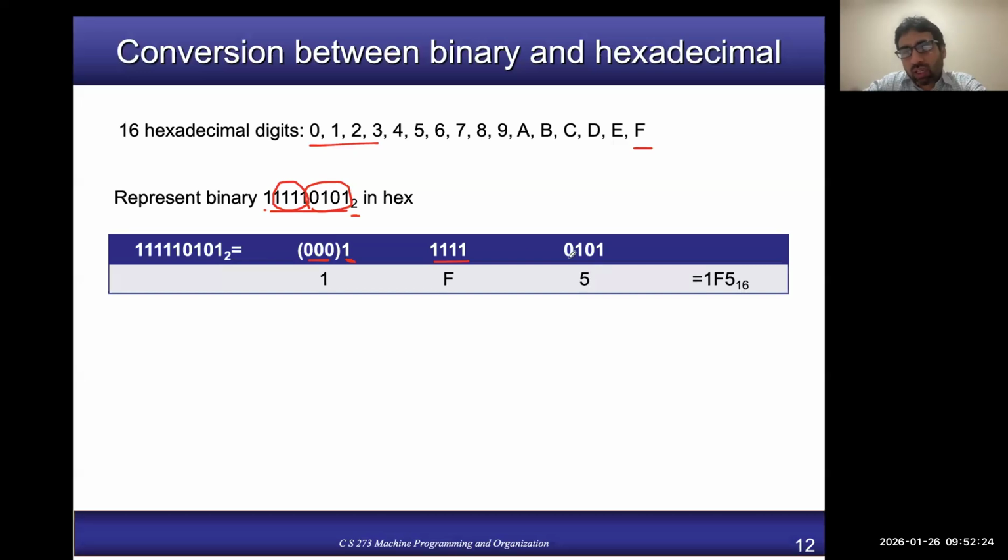Okay. Now you can convert this into the decimal form. So when you convert this 4-bit pattern, what will it be? 5. How can you convert? You can use the weights. Let me do it quickly. 1 into 2 raised to the power 0, plus 0 for this one because the bit value is 0, plus 1 into 2 raised to the power 2.